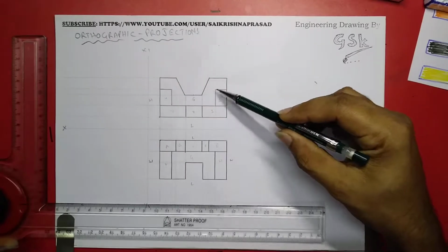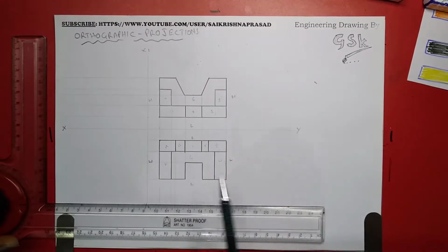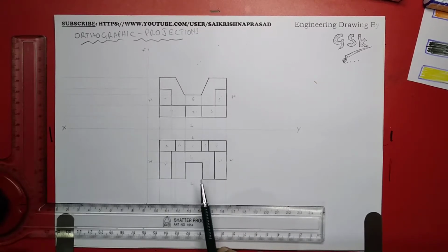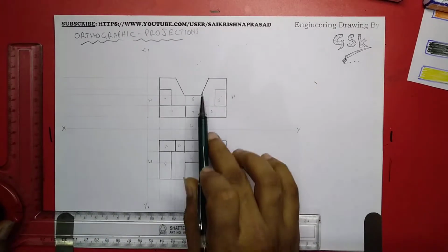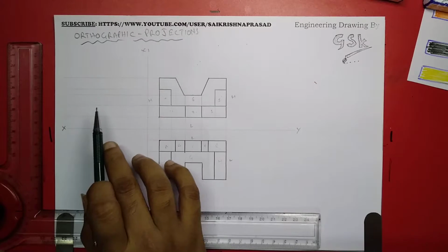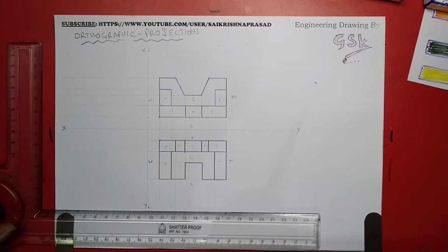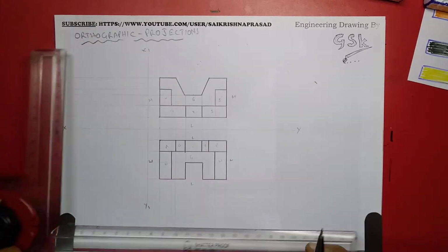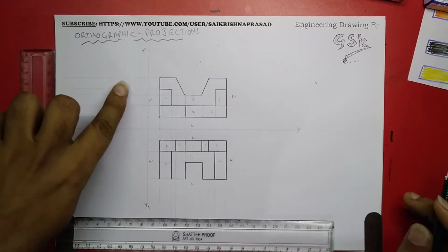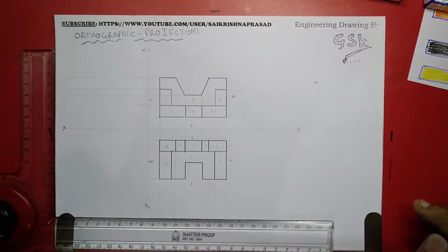While drawing the front view, we had drawn length and height. Here we have the flexibility of taking the height and width from the front view and from the top view. No need of measuring any of the dimensions. Just from the intersection of front view projectors and top view projectors, we can draw the side view.